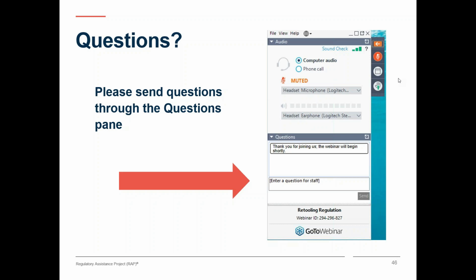For residential EVs, it's quite a different thing. I have an EV. If there's 6 houses on my street that are connected to a single transformer, if 3 people were charging electric vehicles at the same time, it would use up all of the capacity of that transformer. Smart chargers are the answer, making sure that we don't have too many people charging all at once. And the Minnesota pilot of the utility providing the smart chargers is enabling the utility to control those chargers so that the customer gets a charge when power is cheap, but also is controlled to make sure that they're not overloading the local transformer or circuit when they're charging.